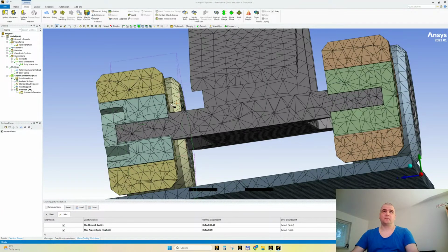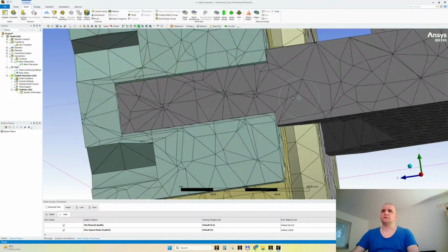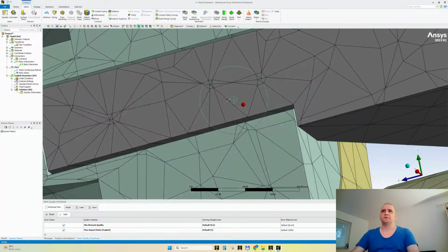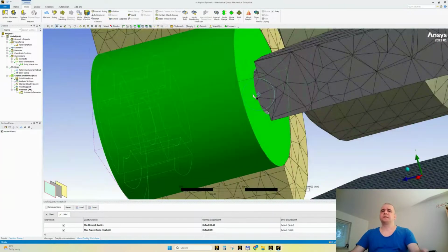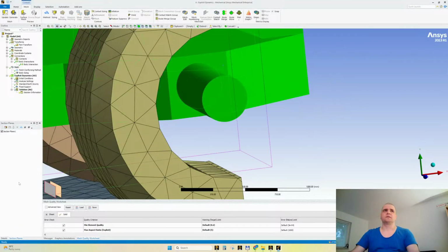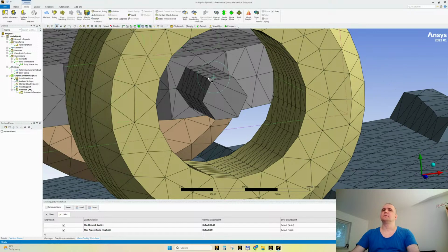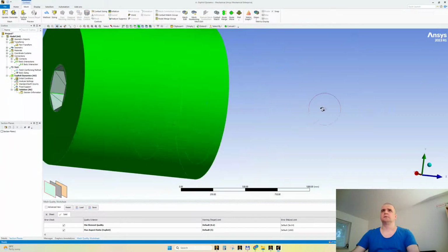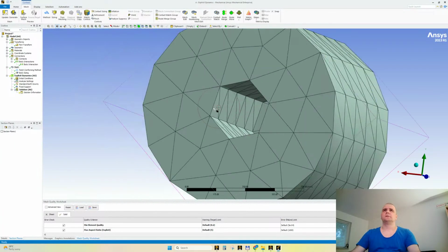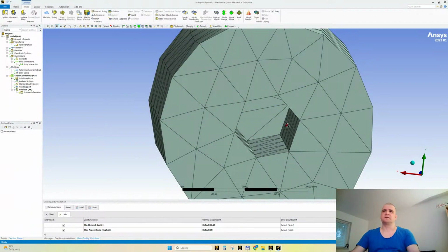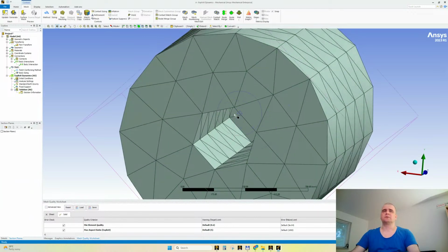Most perfect geometry. Yes, I'm an engineer after all, so please excuse my French. I'm not sure that the mesh is... you see, it's kind of hexagonal. If I remove the, look here, it's hexagonal, yes. And the problem with a hexagonal mesh is I cannot properly define a revolute joint. I need to have something closest to a circle or to a cylinder, let's say.